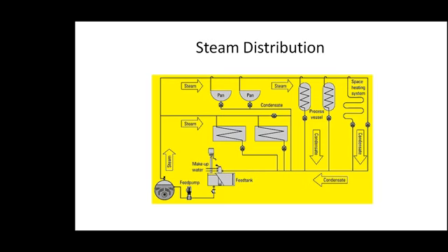So to avoid that, the steam trap needs continuous monitoring, and the monitoring can be done by several methods. We have infrared thermometers where you see what the temperature is here. Using the infrared technique, if steam is passing, the temperatures are the same before and after. If only condensate is flowing, there will be a drop in temperature here. So that will tell you whether the trap is working or not.